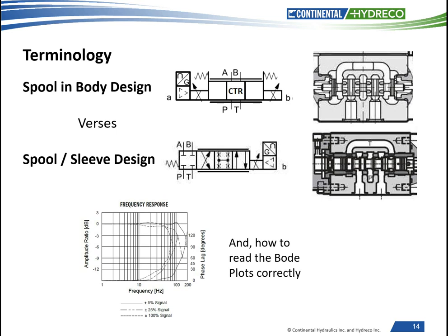Again, they are additive. When estimating what type of system performance can really be achieved in the real world, start looking at how many hertz a selected valve in reality can do at the 30 or 45 degree phase lag points. These are also key points to really look at when comparing the performance of one valve manufacturer to another. You will see a big difference.